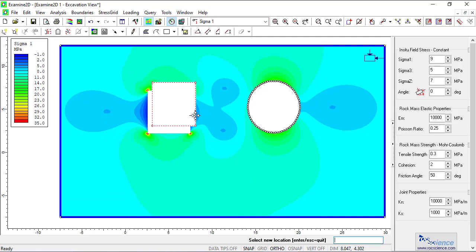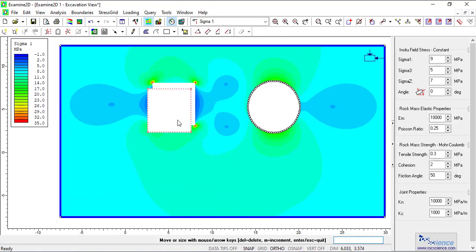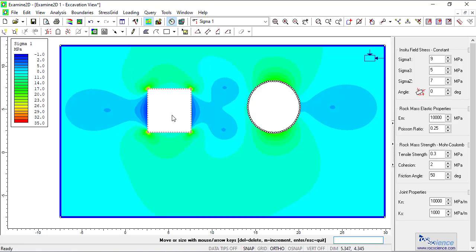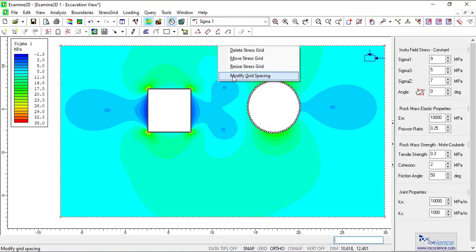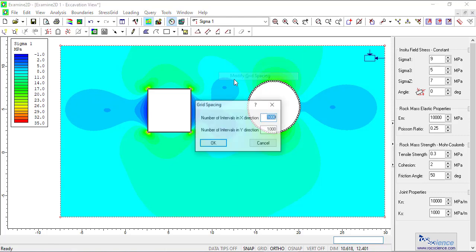You can see it takes a bit more time for the manipulation to catch up in the model. So this is a little bit excessive. So I'm going to step the external boundary grid spacing back down to a reasonable number.